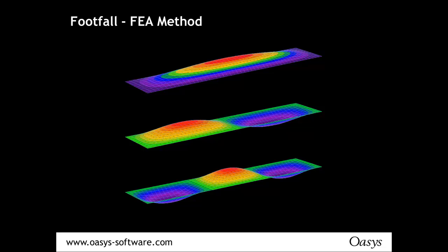If there's no live load, you get the worst maximum response values, but if there's no live load, there's nobody there, and therefore is it a problem? Conversely, if you've got 100% of the live loads, there's a lot of damping and a lot of mass in the system, and that tends to produce lower response values. It can be an interesting exercise to vary the live load and see what difference it actually makes to your structure.